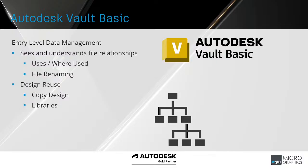If you go to rename files, you need to now change the part numbering scheme and you want to update the file names to match. Vault can repair the relationships between the assembly and the renamed part files. Normally, that link is broken. Vault or Inventor says, I can't find the related parts because the names are different. Vault automatically updates those relationships. This allows for very easy design reuse.